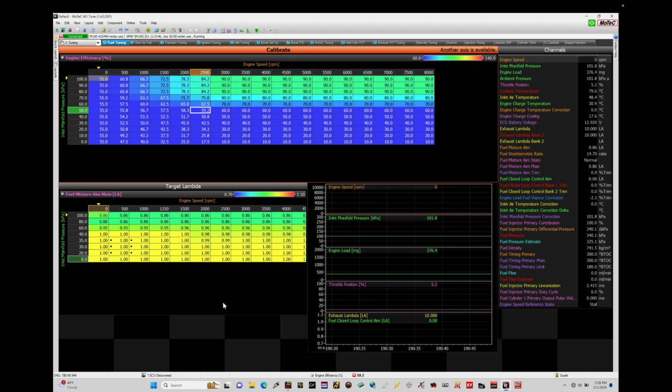When we're talking about a single throttle body with an intake manifold plenum, we'll find that we have a relatively linear relationship between our throttle angle and our manifold pressure changes. Once we switch over to individual throttle bodies, we're going to have a completely non-linear relationship. As we give some throttle input, our inlet manifold pressure may go from something like 30, 40 kPa vacuum at idle all the way to 100 kPa almost instantly. And as a result, we'll have unpredictable fueling.